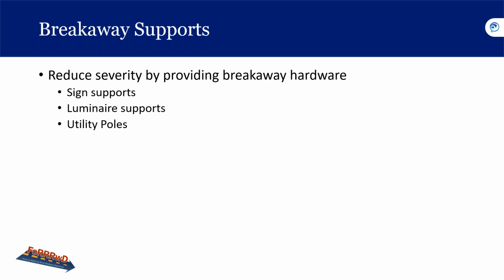If we recall from session 2, the MUTCD requirements for curve signing, similarly, the MUTCD requires sign supports to be crash-worthy because they are fixed objects with the potential to harm the occupants of the vehicles. Crash-worthiness is determined by MASH standards, and each vendor or agency is responsible for testing and assurance. Luminaire supports and utility poles come under AASHTO guidance. There's a booklet called Structural Supports for Highway Signs, Luminaires, and Traffic Signals, which you can look up.